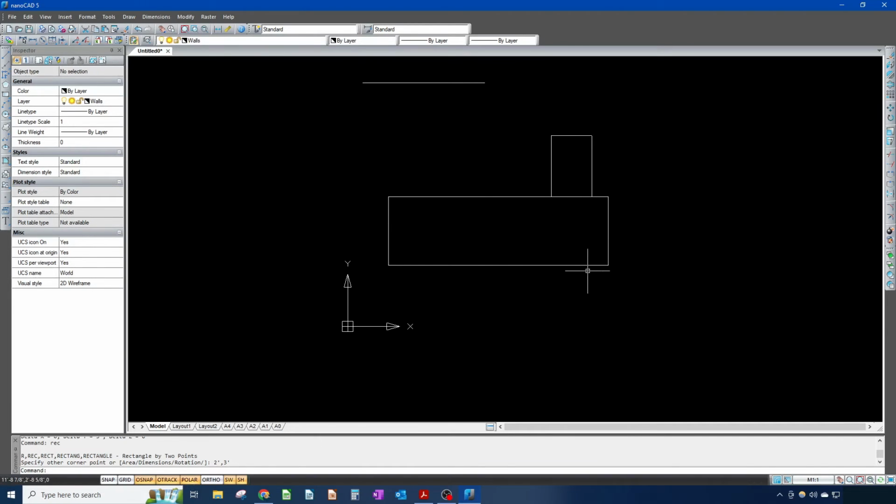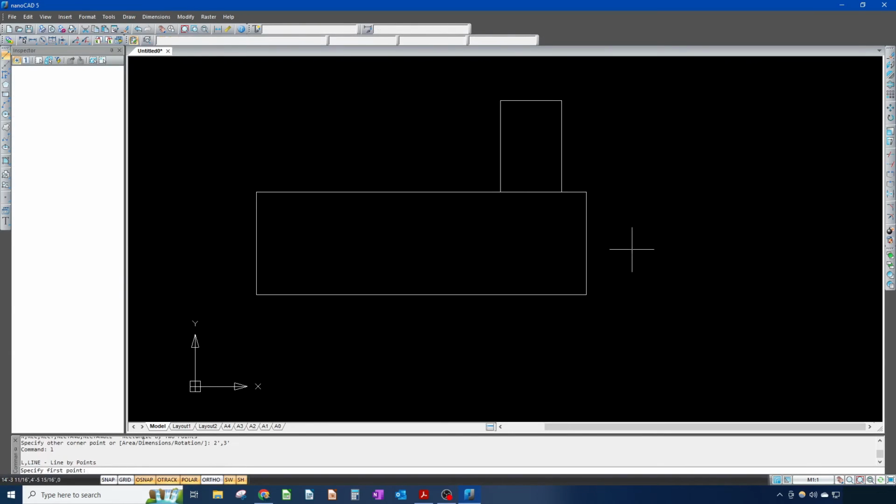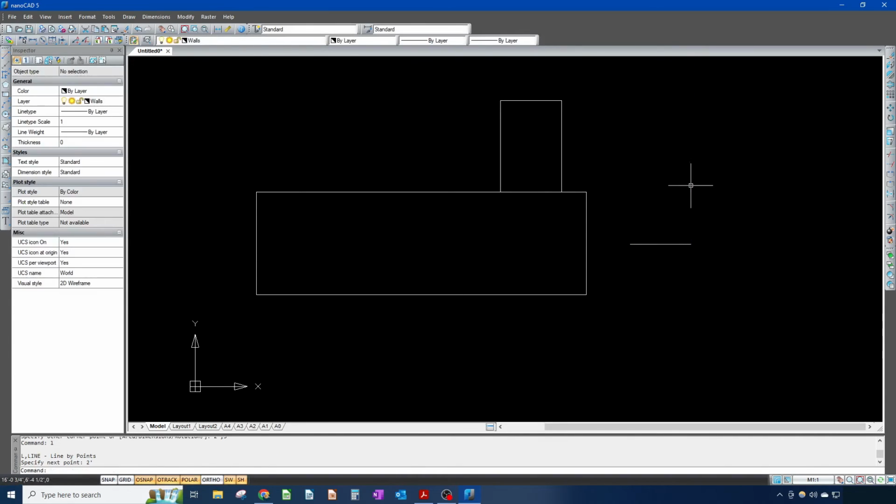Again, whenever you're drawing linear dimensions like in a line, so if you were to L space, if you were to draw a 2-foot line this way, you don't need the @ symbol. Only when you're doing Cartesian coordinates.